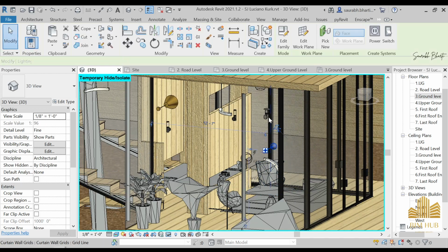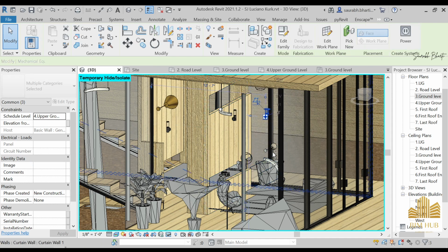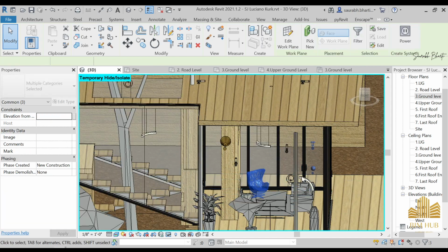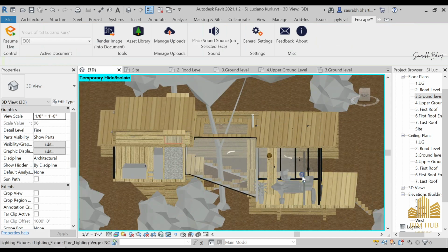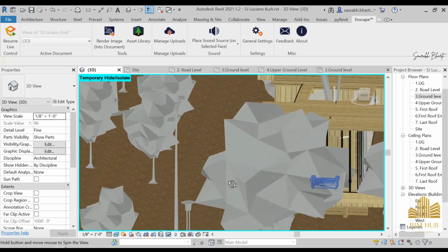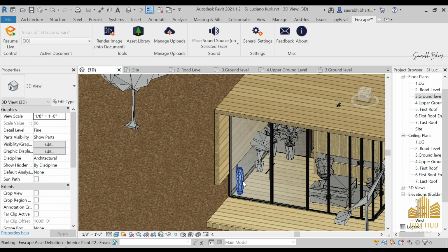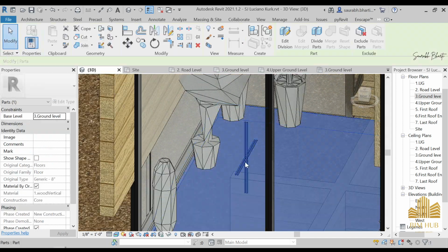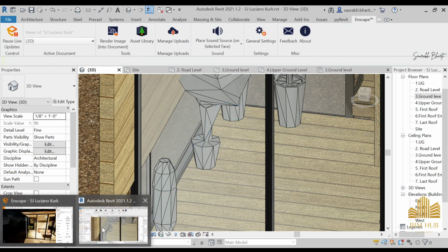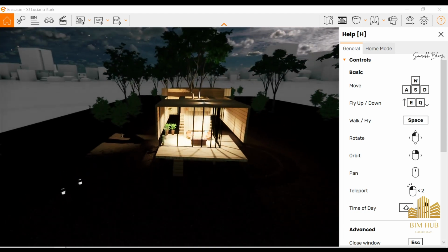And now you have to just delete this lighting. Just delete all of this right now. You don't need these things, and not this one. So press shift, then remove this one, delete it. And what other family do we have over here? This part and this part, just remove it. And what else? Let me check if there's something left. No. So press HR, and now you can see that we have one more family. Select this one, delete this one, and now you can resume live update and just go to this, and now you will see that we have perfectly rendered our project.